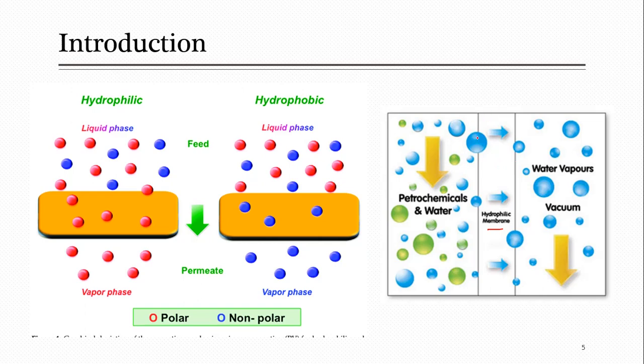Now here, when we are decreasing the pressure, we are creating the vacuum. Due to this, you are decreasing the surrounding or ambient pressure, and when ambient pressure is reduced, the boiling point is reduced, and they can easily boil even at low temperature. Due to this, they are converted to vapor. For example, with water at ambient pressure you would need a temperature of 100 degrees C, but when you reduce the pressure, it can boil easily even at a temperature below 100.